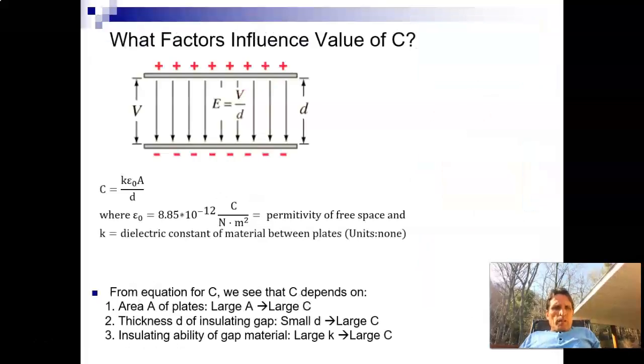So if you look at the equation and you're designing a capacitor and you want to store a lot of energy, how do you do it? Well, the first is you have a large plate area A, right? And one way of doing this is you can actually make these at home. You can take 2 pieces of tinfoil, 2 long strips of tinfoil, and stick a sheet of waxed paper in between them. Okay? And then you have 2 conductors separated by an insulator.